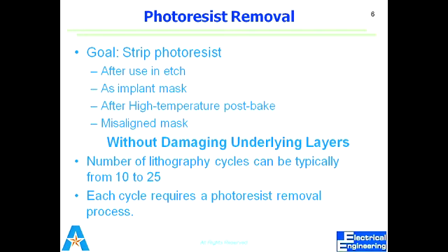So if you could not align the photolithography process properly, if there was misalignment, it means that in the next photolithography process you could not pattern it the way you wanted. So you want to rework this process. Due to the misalignment of the mask, you need to remove all the photoresist. Again, you need to make sure that no photoresist strips are left and you need to remove it. So these are the different cases where you need to remove the photoresist.